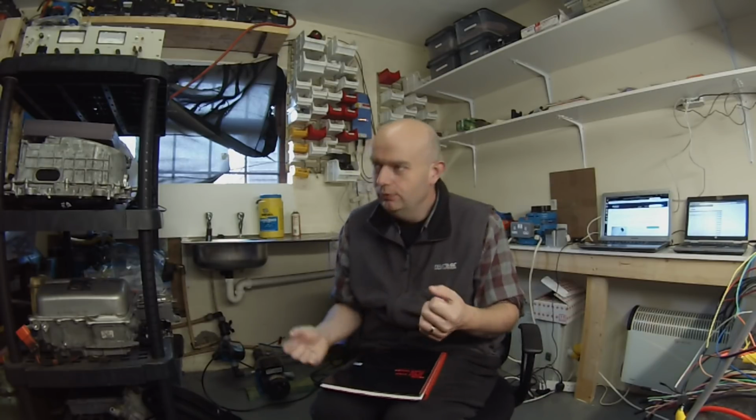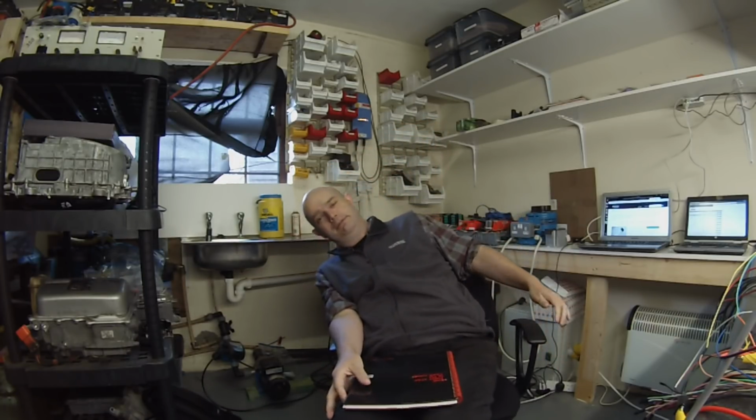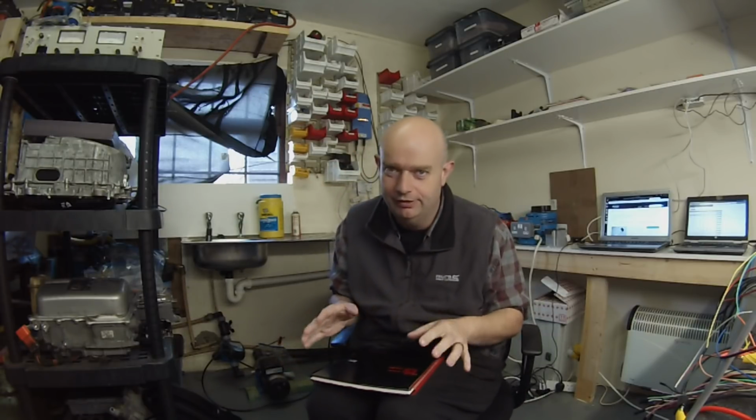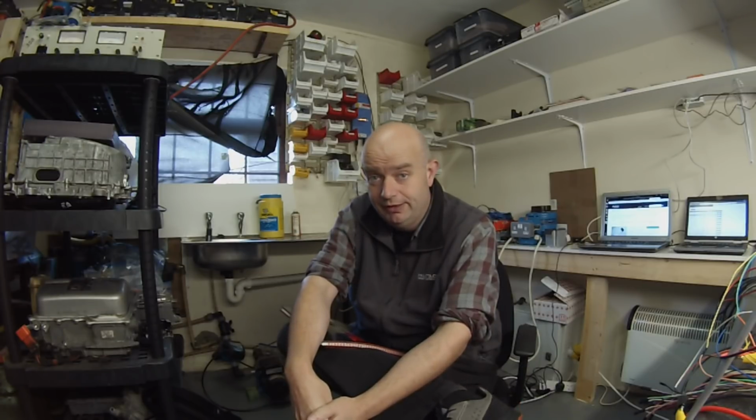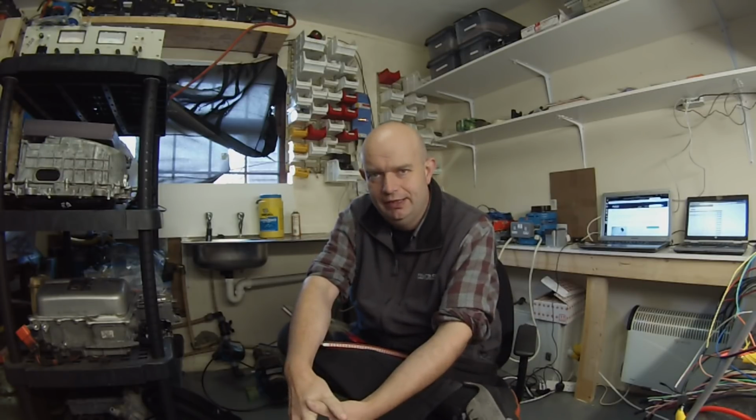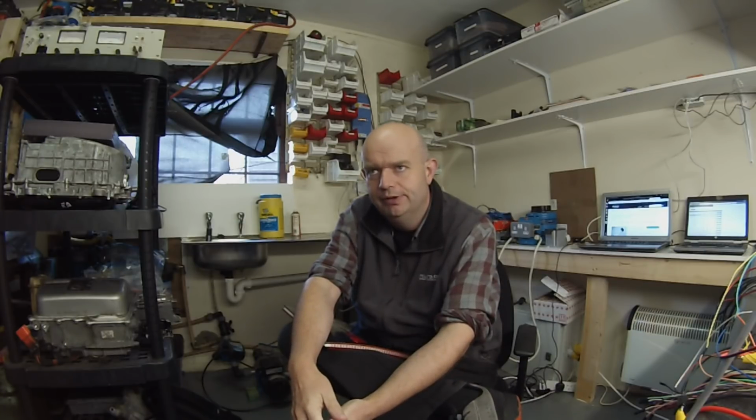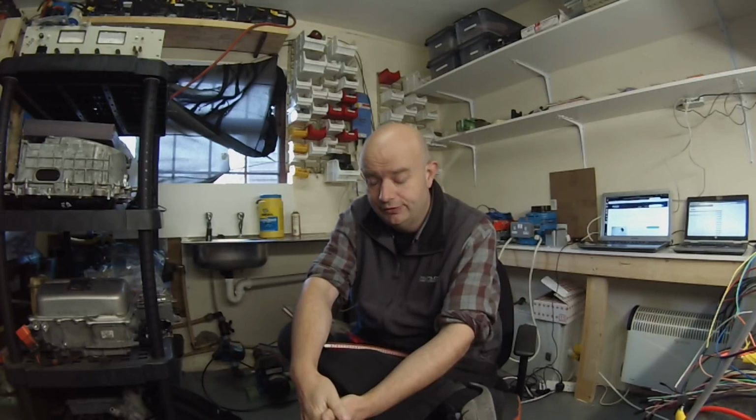So let's look at the inverter failures first. Now, when I say exploding inverters, that isn't driving along, boom, flames, we're not quite talking about that. What we're talking about is failure of the IGBTs in the power stage. Now, you may recall from the video and the live stream that I did after it that I was focusing in on two things as being the potential cause for the inverter failures.